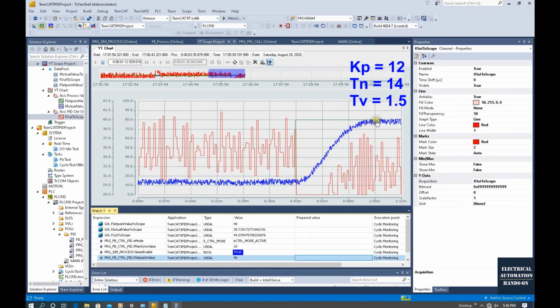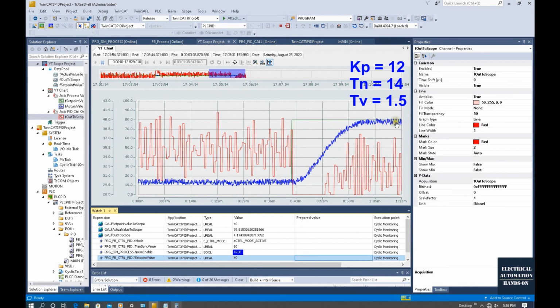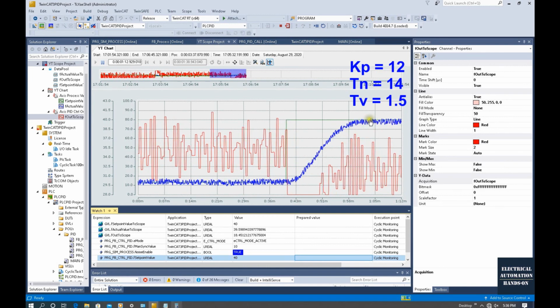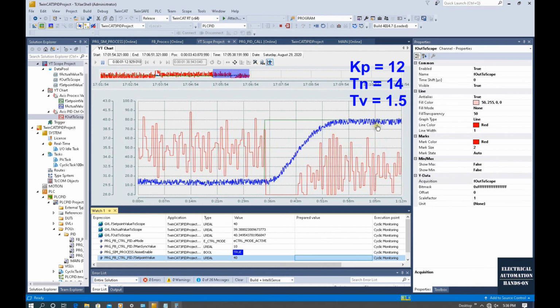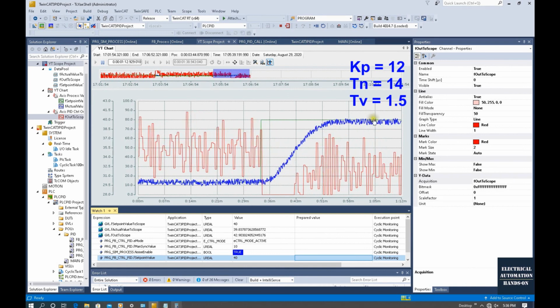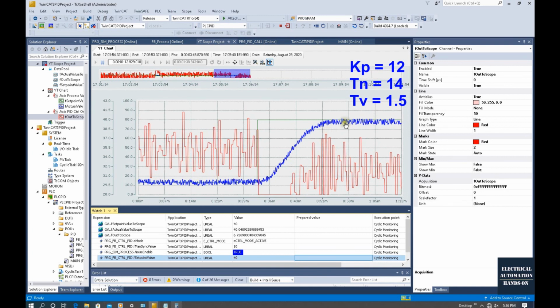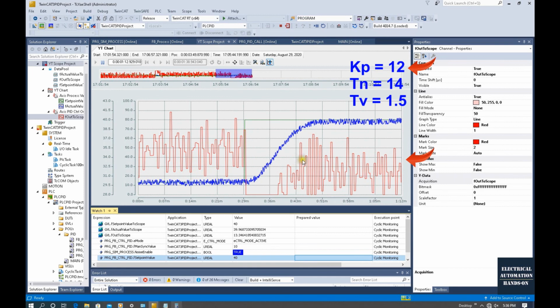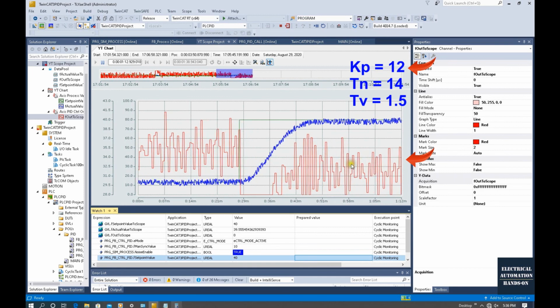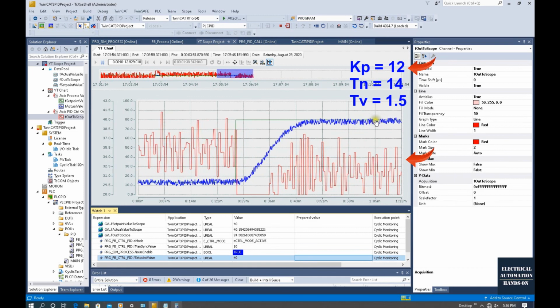So we will see this process value reach this set point. And this system also includes the noise. All in all, this process behavior shows really good. And this control parameters basically can work for this process. Maybe the gain could decrease a little bit. That can make this PID output not so sensitive because this process has a noise.